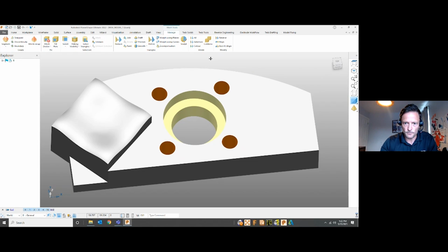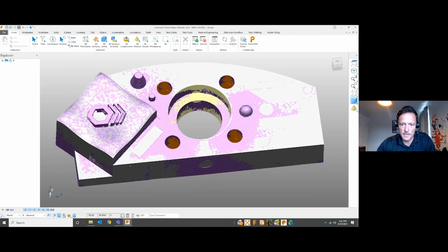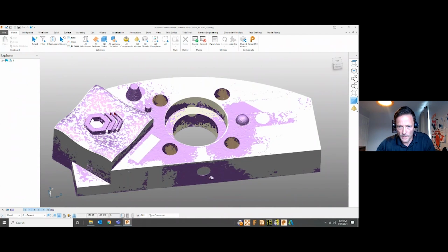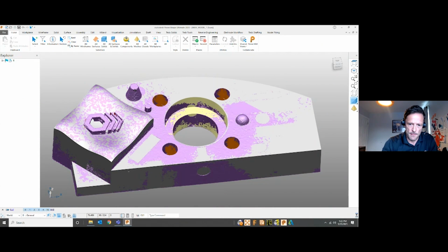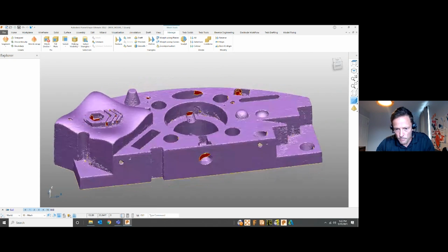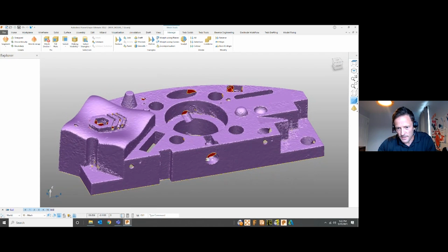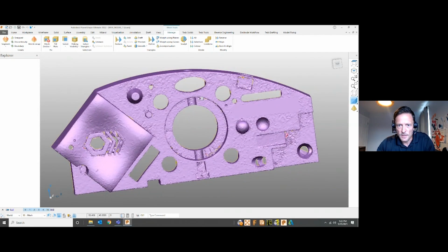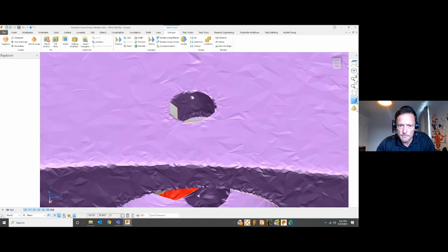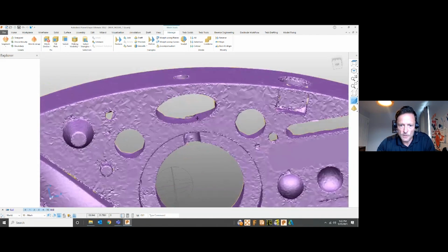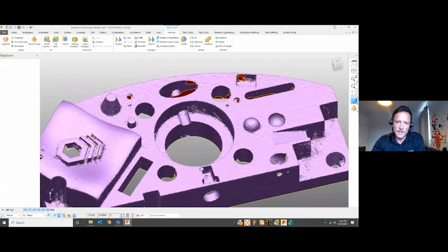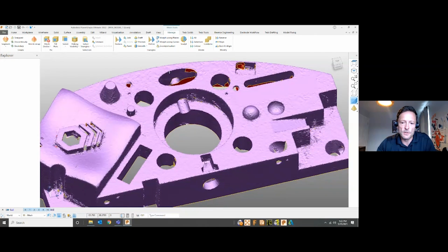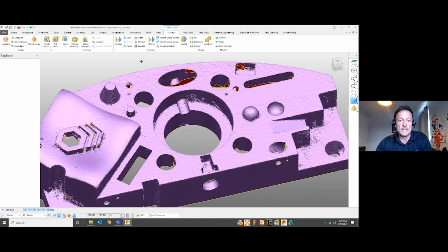Okay, so now let's just give Alex another hole to machine here. And this time we're going to be going through from the side here. And once again, scanning, it's captured some data at this end, minimal. Well, actually, this one was probably good, but what's going through on the side again is minimal stuff. So let's see what we can do there in this scenario. And again, it's perpendicular to that front face, and PowerShape's going to hopefully allow me to lock onto that because it's within that preset alignment angle.